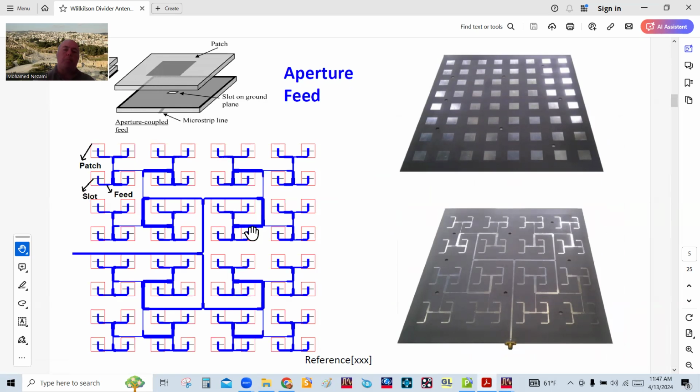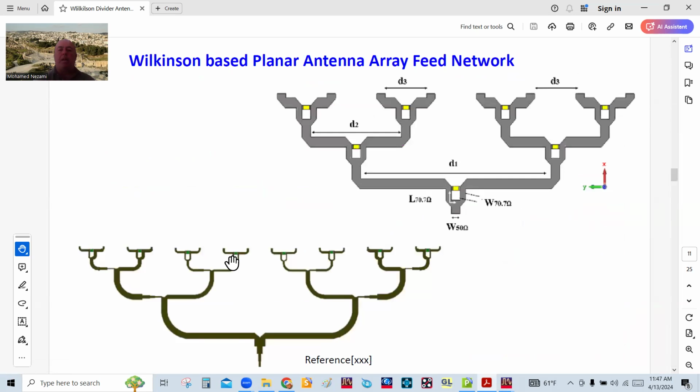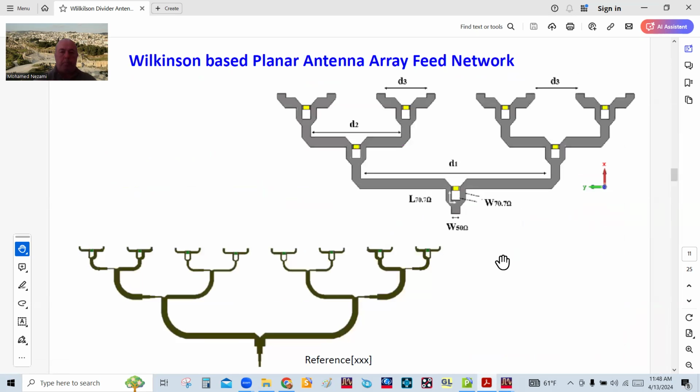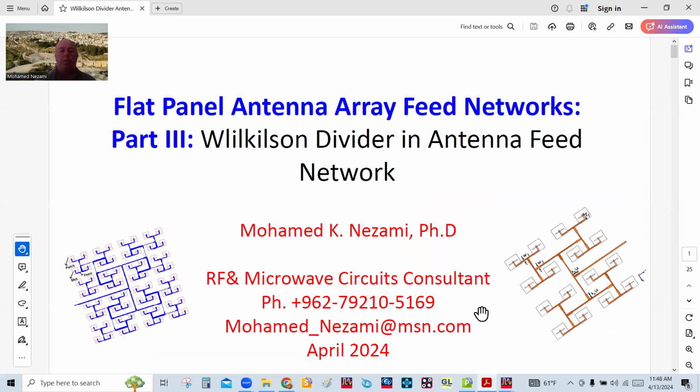So that's why a lot of people end up using T-junctions, unless of course they have a case like this, where it can all be done planar, and the resistors can be surface mount resistors. So again, all of these things you really need to EM simulate. For these designs, we don't guarantee that you're going to get performance like this, because this is based on S-parameter representation of these segments, whereas in the actual layout it's a little bit different. Okay, so you do need EM simulation.